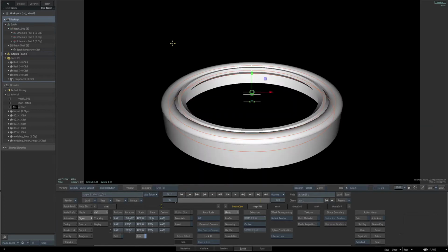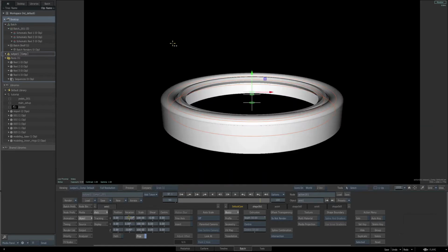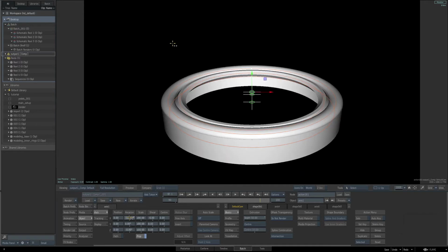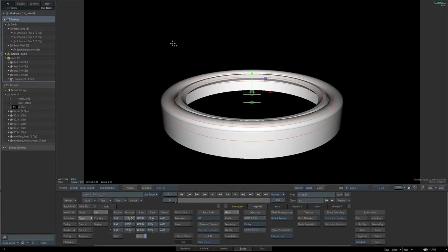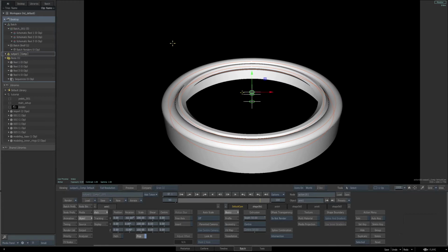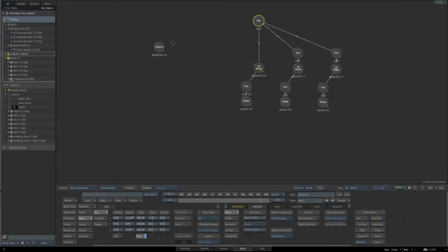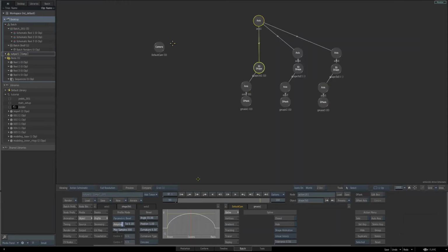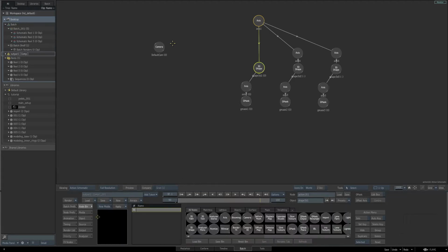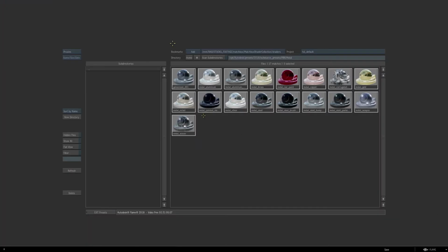Then let's select the main axis for all the shapes, and then we can rotate it in the view to see what we've created. Now it's time to start assigning some materials to it. Select the first 3D shape, go back to our node bin, hit the S key with your cursor over the node bin, double click on Substance PBR. The Substance PBR options appear.